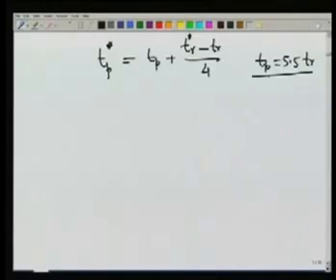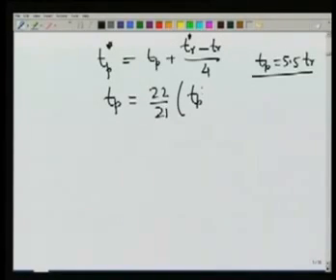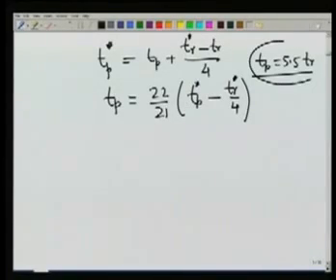So using these equations, we can correlate the standard time to peak with the observed values of time to peak and rainfall duration, as Tp equal to 22 by 21 Tp star, which is a rather straightforward operation by just substituting this value here and solving the resulting equation.